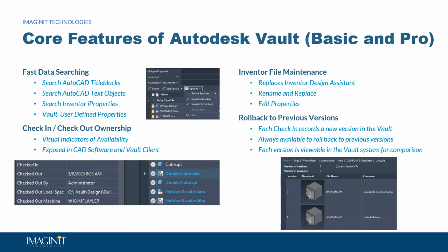Some of the basic functionalities that you know and enjoy today with Vault Basic, including Pro, is kind of a baseline here, right? Fast data searching using that SQL database. So the fact that it needs to be performing at its utmost peak performance is very important. How you set a vault up and how you set up different allocations of the drive and IIS folders and how you clear the logs and such can be a very important aspect to make sure the performance runs smooth.